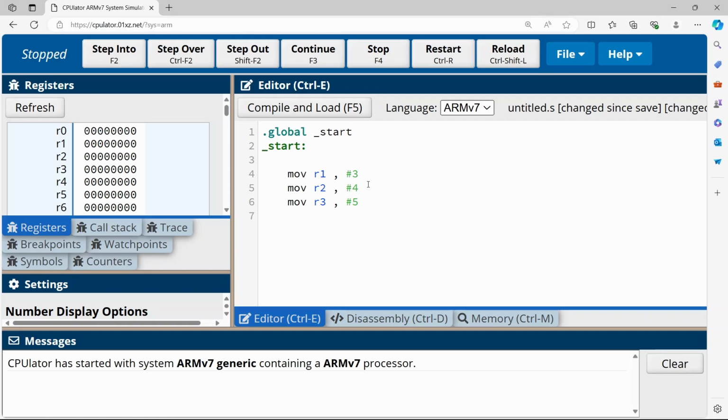Now let's write a store multiple instruction. There is no necessity of writing the store multiple instruction in capital case, but for my personal satisfaction, I am writing it in capitals. Let's take the register R0, where the address in R0 will be taken as the base address.